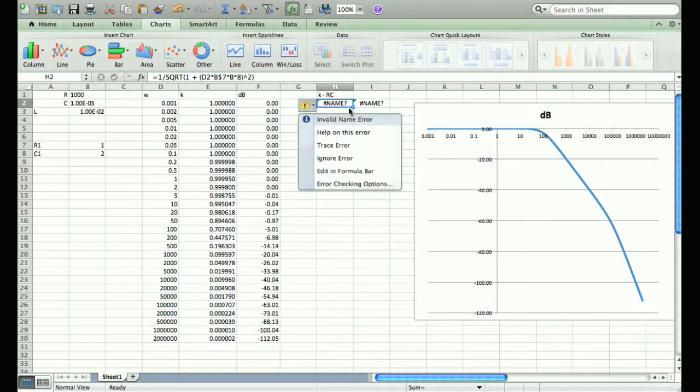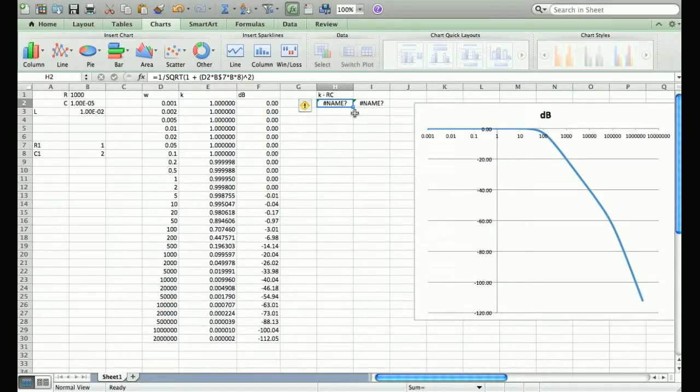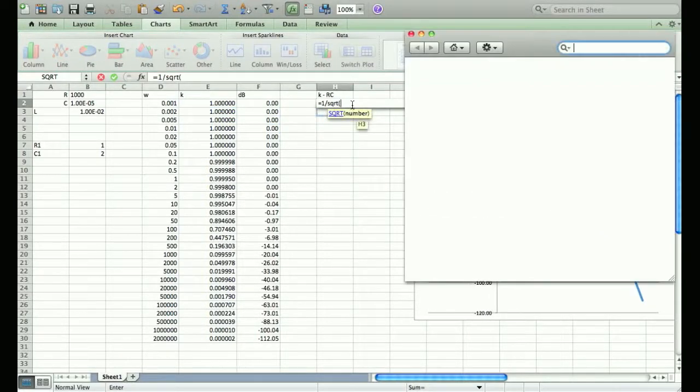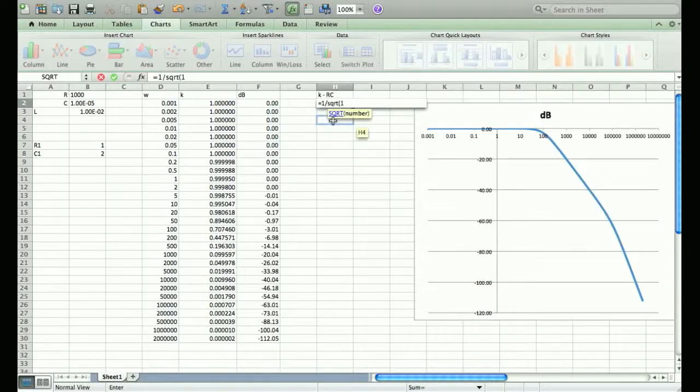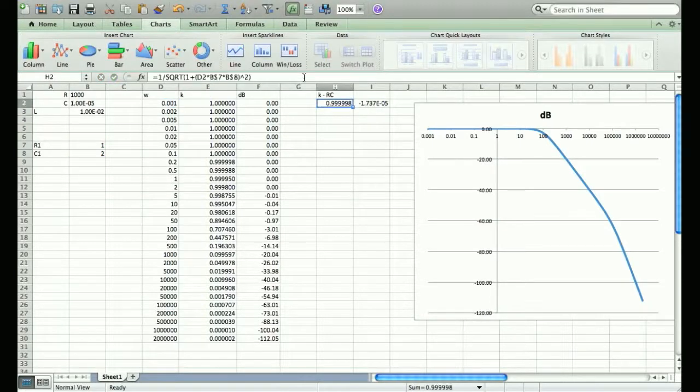If you have an overdamped solution, here it would be zeta equals 2, you're still going to get the kinks, but the solutions to the characteristic equation tell you where those kinks are, and that was supposed to be the main take-home message for the day: by solving the characteristic equation you can see where this thing kinks and where it starts to look real, and when it's overdamped, where it starts to look imaginary. Okay. So I just did the second part without realizing they wanted me to do it as a separate thing.